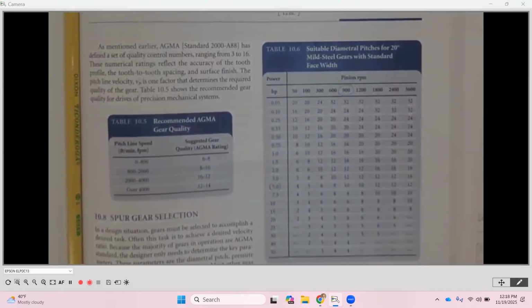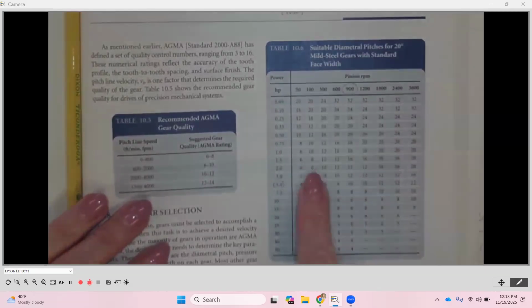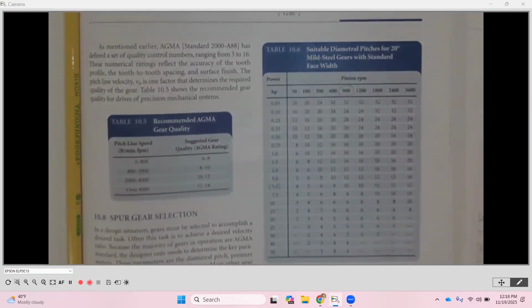Okay, so these are going to be standard gears, just like the fastener industry. As we had mentioned the last time we were together, the American Gear Manufacturers Association governs these standard numbers. Okay, so you're going to notice that the numbers on the inside here are going to be the standard diametral pitch numbers that are on that list, as deemed by the American Gear Manufacturers Association, okay?